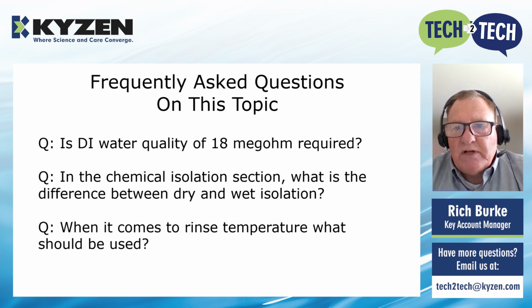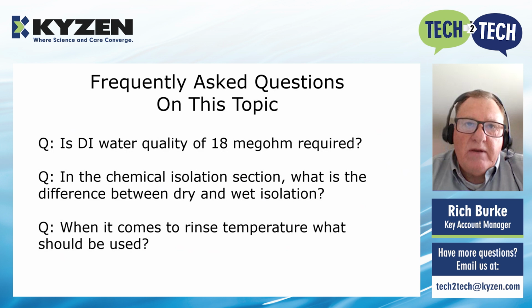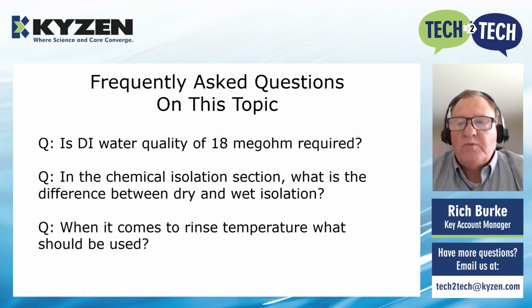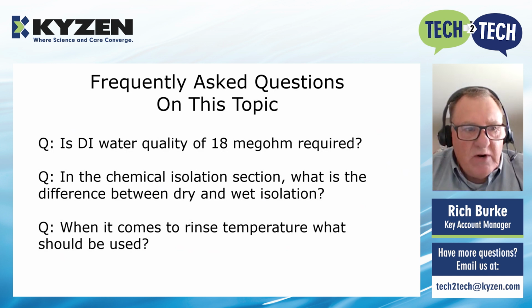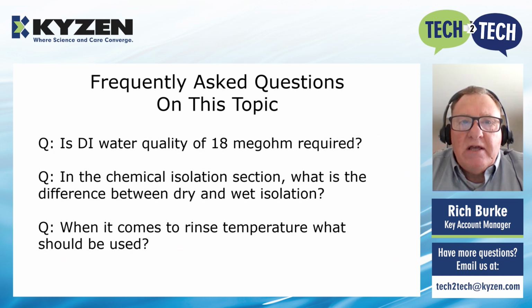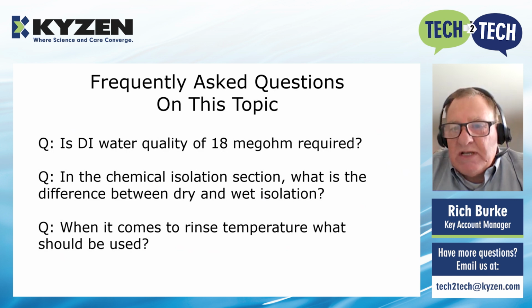Last question, when it comes to rinse temperature, what should be used? Again, IPC does talk about this in the spec, and it says the higher the better, or highest possible, without degradation of components and assemblies. And that would be true. I would say keep in mind too that when we're using DI systems for closed loop, the DI systems degrade over time as we get into an excessive temperature range. So we want to keep that in mind. But in principle, I would say be in and around the wash temperature range. It would be in most cases ideal.